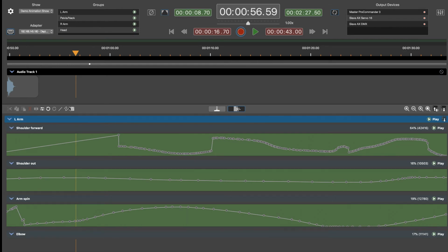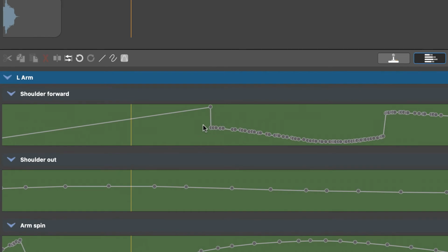To get into data point editing, we're going to click on this icon, and you'll see both digital and analog representations of your recording or drawn data points. This follows the workflow of most common programs in that any single point can be grabbed and moved horizontally or vertically within the timeline restraints. As you're clicking and dragging, you'll see that level displayed as you move it up and down. So if I'm moving it down to 10% or 19%, you'll see that value as I move that point up and down. To the left and to the right, by default, that's going to linearly interpolate previous values to next values, as you're seeing here.